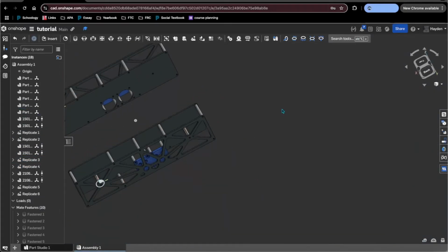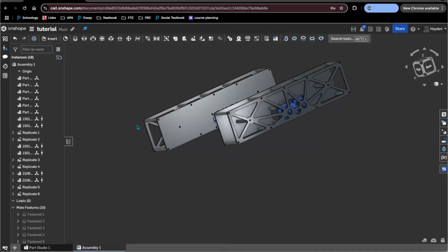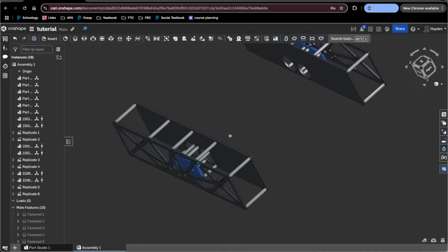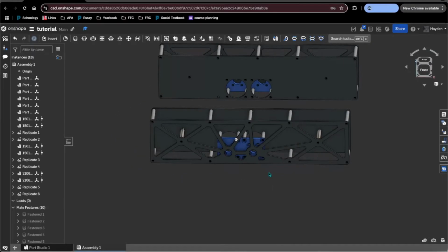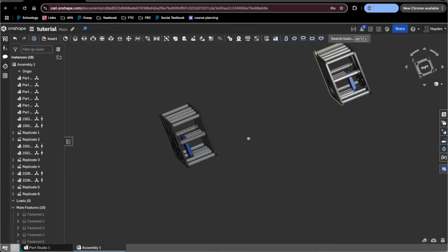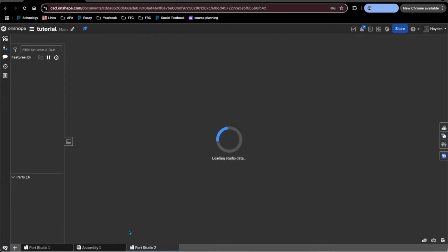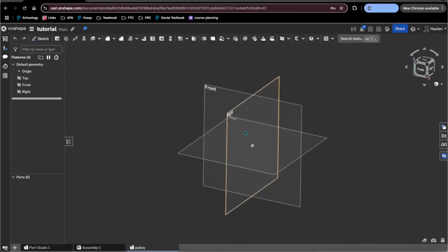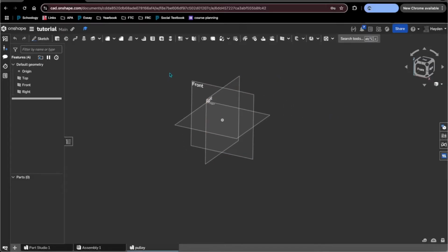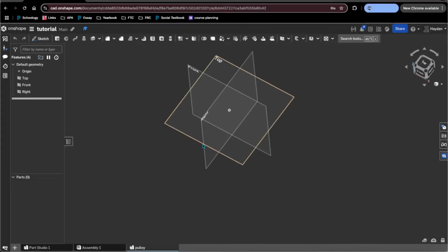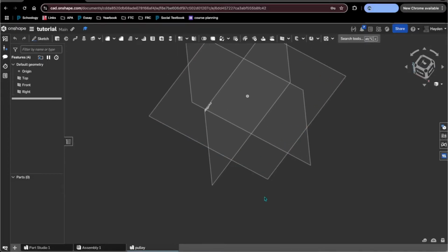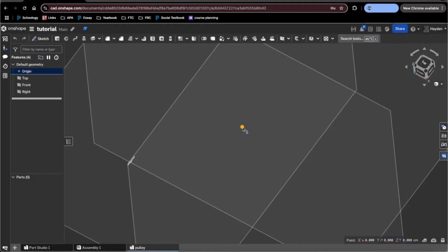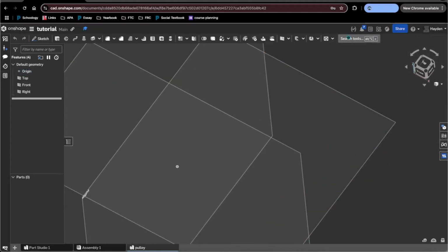Okay, perfect. So now we have our rack shafts on, and this drivetrain is basically assembled in terms of non-moving parts. What we're going to do now is create a new part studio, and we're going to rename this to Pulley. Now, this is where things are going to get actually rather interesting. We're going to use a derived function, and what that essentially does is it inserts a part studio from another document. In this case, we're going to insert a configurable pulley that will be 3D printed.